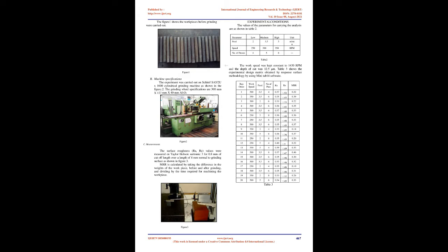2. The residual stress formation during the grinding process is due to plastic deformations and phase transformations, which are affected by grinding parameters such as speed and feed rate. It is known that differences in speed of the grinding will produce different residual stress profiles. Along with high rotational speeds of the workpiece, there is an increase in the tensile residual stresses. This is because of the heat which is created due to higher friction rates as well as other mechanical factors such as the load being applied on the component's surface.